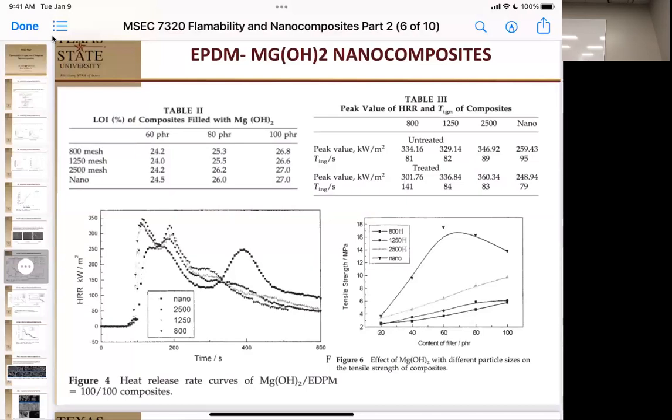And then if you look at the tensile strength of nano versus the macroscopic fillers, we see moderate improvements, linear improvement for the micro, which we expected. And then of course we see the same for the nano as well. We see a max benefit until you start aggregating, and then it goes down. So that was a pretty good one. The net result for especially the peak heat release, right here, the 100 kilowatts lower was a significant pop.